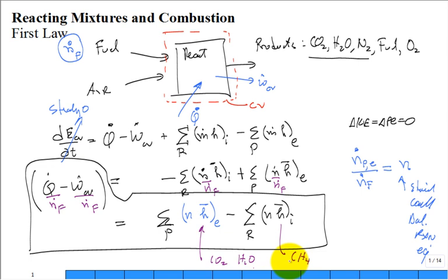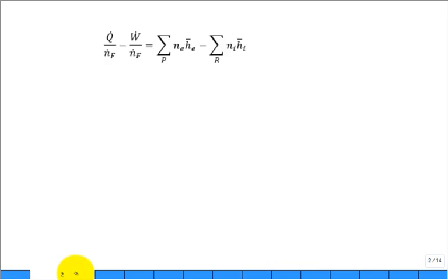You know, basically we had steam in, steam out, refrigerant in, refrigerant out. But now we're conserving species, we're conserving our carbon, our oxygen, our nitrogen, but they're changing groups. And so that goes back to our chemistry. How do I get a common energy measurement for these switching around of the components? So there's our equation, and the challenge is coming up with that molar enthalpy, so everybody has the same measurement standard where it starts.